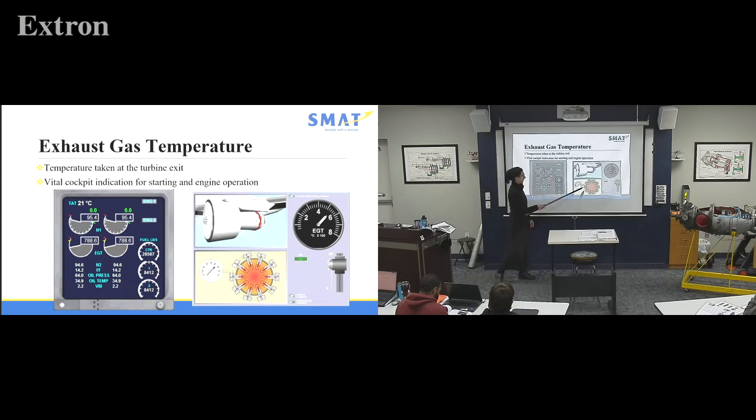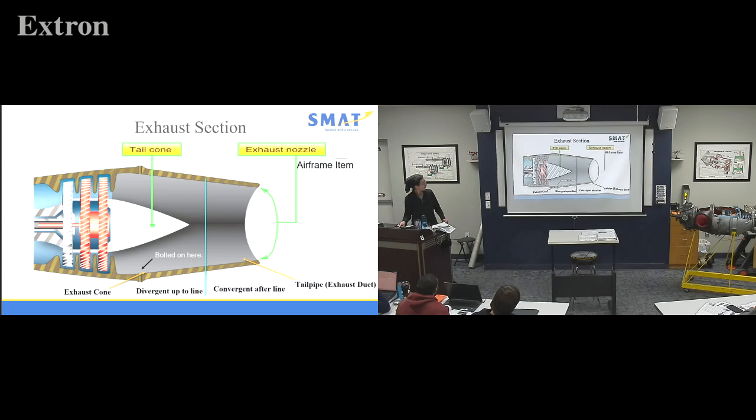But what do you think these thingamajiggies are? Excellent. Thermocouples. They'll put a thermocouple ring around your exhaust where you want to take your exhaust gas temperature. You can have analog dial or nice digital readouts. And not every turbine engine will have an EGT gauge. We're going to talk about, yeah, that picture will work.